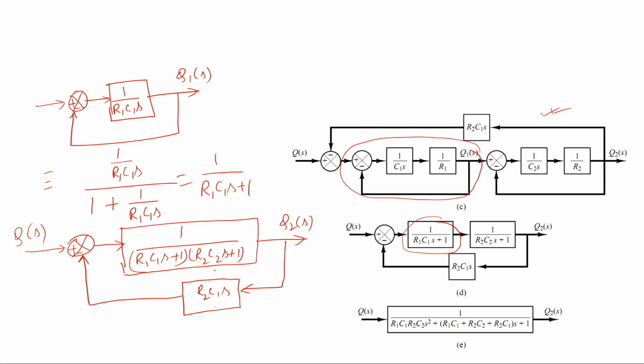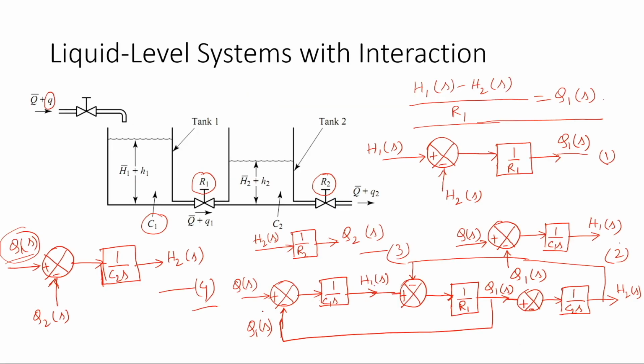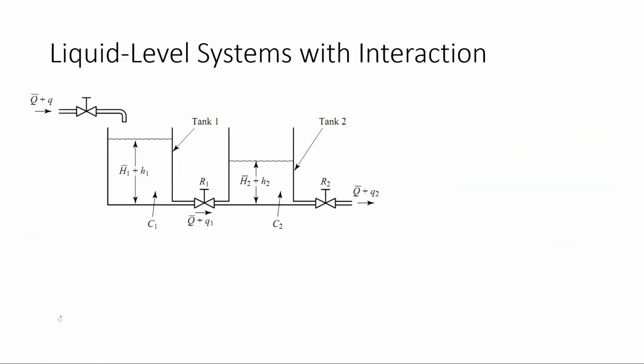So, again this is your H, this is your G. If you reduce it, then again QS is our input, Q2 is output, and in between you will get G by 1 plus GH using this basic formula. So, you will get this type of complex transfer function. You must notice that this transfer function is not the mere multiplication of these two gains, that is, two tanks are basically connected. You can come to here, see here, two tanks are connected like this.